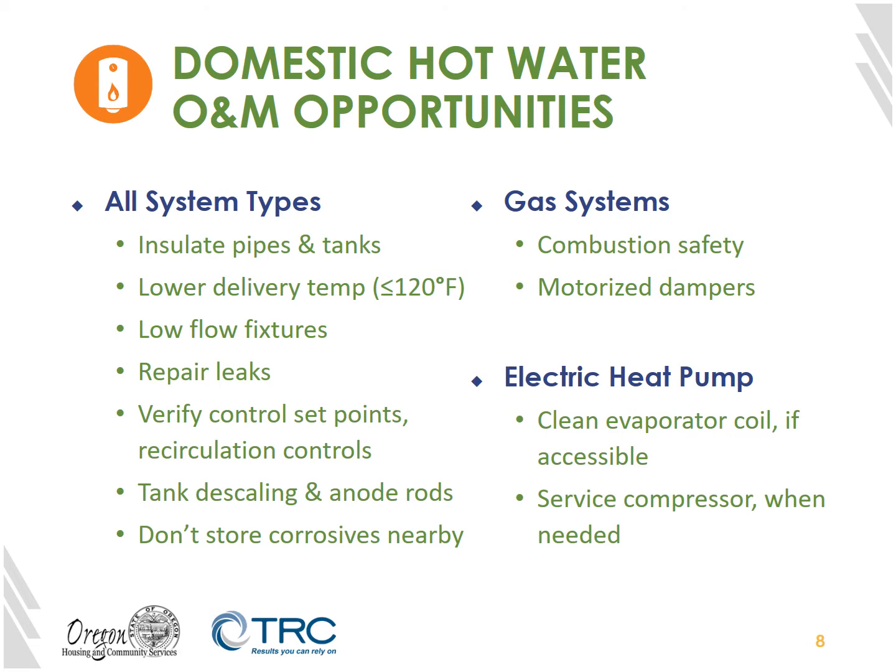And finally, we need to ensure that we don't store corrosives near our water heating system that could potentially degrade the equipment. For gas-based systems, there are combustion safety measures that we need to perform, and we may need to perform maintenance on motorized dampers. For electric heat pump systems, we might need to clean the evaporator coil if it's accessible, as well as potentially service the compressor when needed.